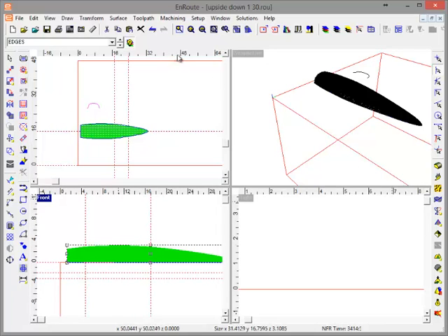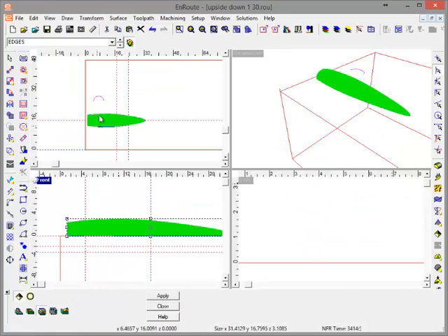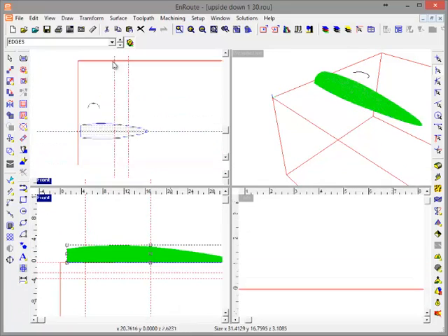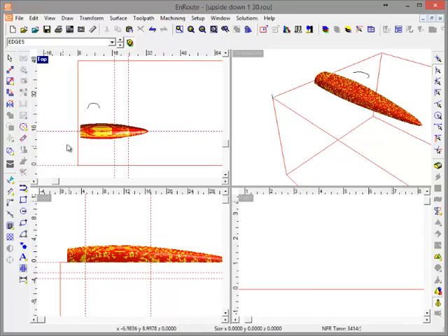So now we're going to go here to the transform menu, and with our mesh and our 2D outline selected, we're going to hit apply mesh from the surface menu. I'm just going to do beveled. I'm going to hit add and apply. Now I can always tell if I see them occupying the same space at the same time.